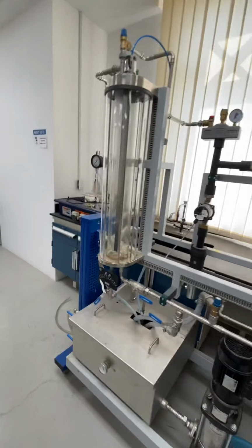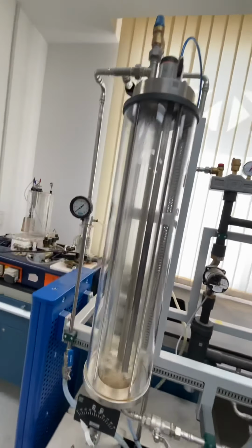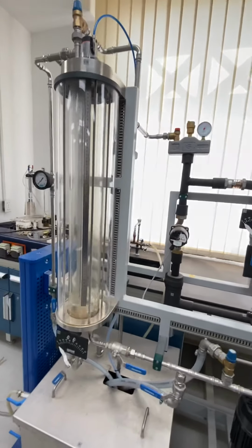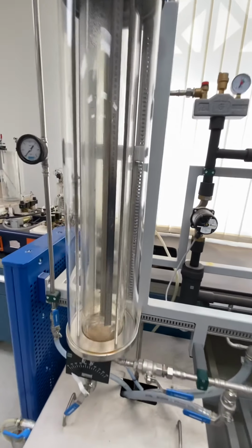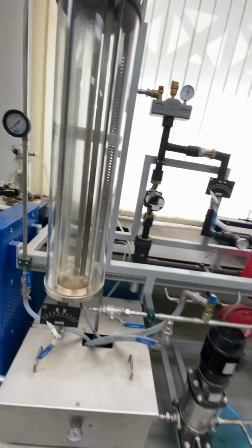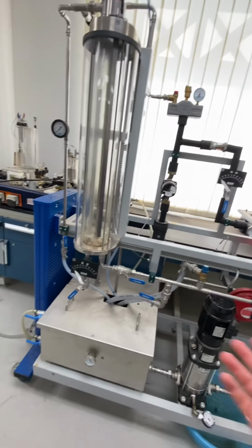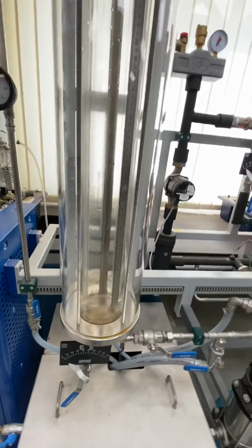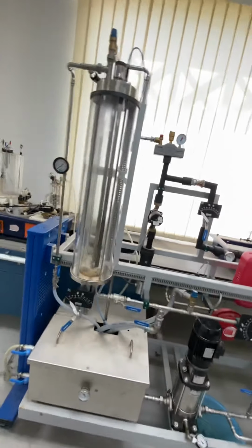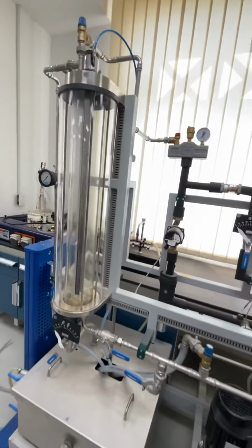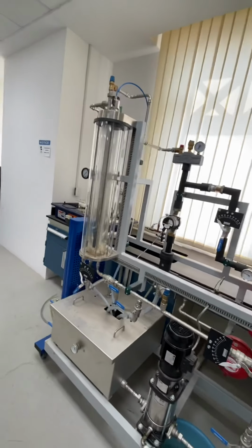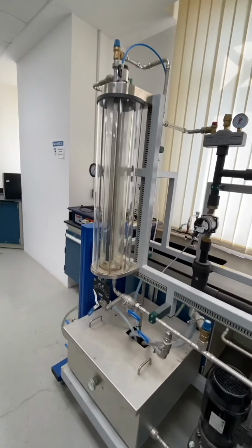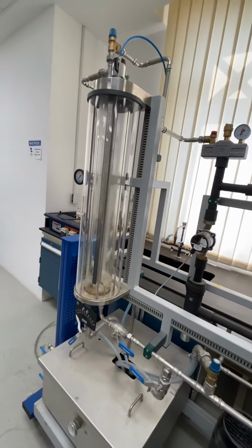Okay, so the level, as we all know, guys, in this kind of tank, which is a fixed roof tank open to the atmosphere, is affected by the inlet flow rate and the outlet flow rate, how much is flowing into the tank and how much is flowing out of the tank. For steady state constant level, the control system has to make sure that the flow into the tank is equal to the flow out of the tank.